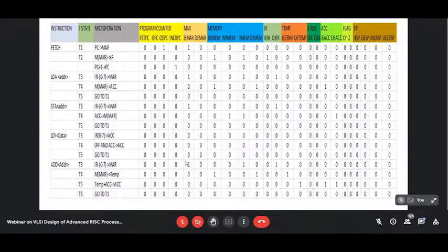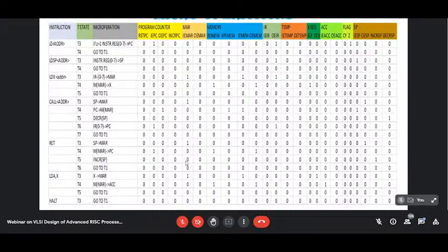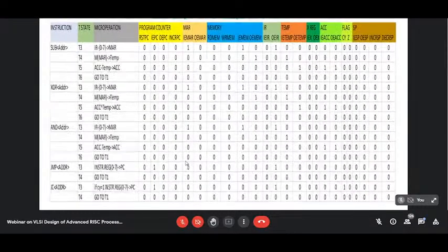That's all. Now what has to be done? Go to T1. Means now again it will go to the next fetch cycle for fetching the next instruction, that is written by go to T1. So in that way, we can write the micro operations for all the instructions. Once we write the micro operations, we find the maximum number of T states required. So here we are finding that T6, so 6 T states will be required.